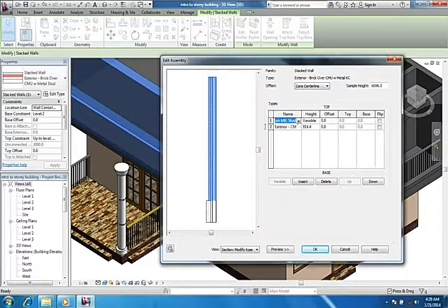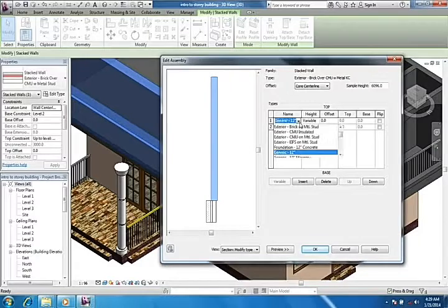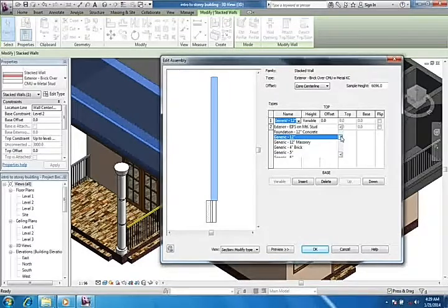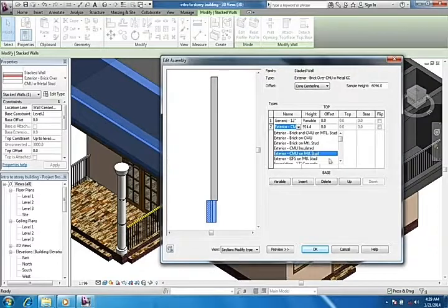Select this point, number 1. You can see I have 2 walls, wall 1 and the second one. If you look at the height, the down part is 914.4 mm. So I'm going to select this side, then look for a less thick one. Let's select 12 inches, which is the thickness of the basic wall. I think it's okay. Now let's go to the down part of it and select.